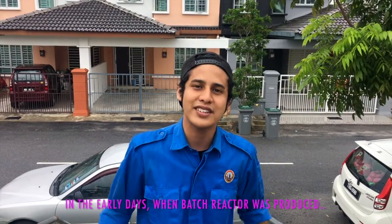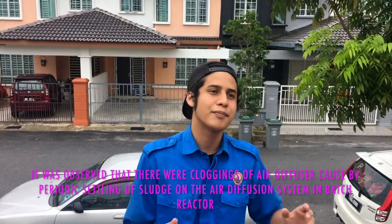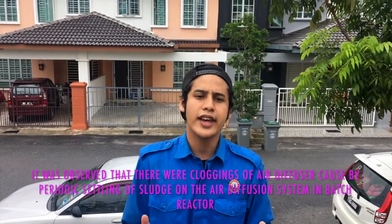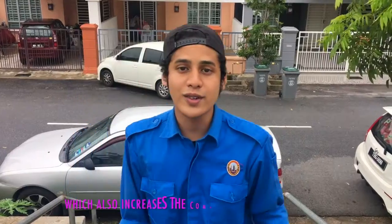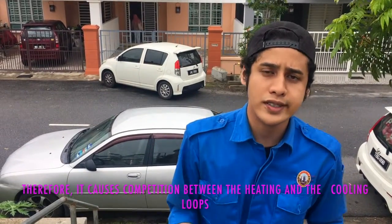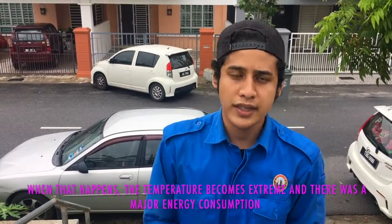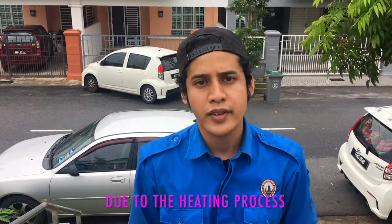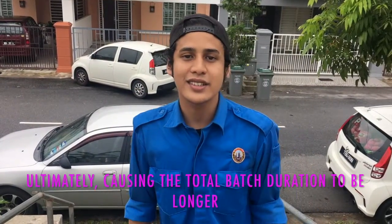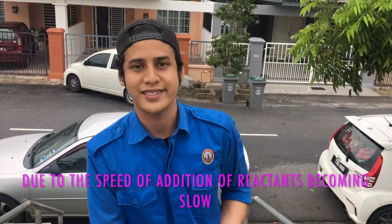In the early days, when the batch reactor was produced, it was observed that there were cloggings of the air diffuser caused by the periodic settling of sludge on the air diffusion system in the batch reactor. It also increases the complexity of operations. Therefore, it causes a competition between the heating and the cooling loops. When that happens, the temperature becomes extreme and there is major energy consumption due to the heating process, ultimately causing the total batch duration to be longer due to the speed of addition of reactants becoming slow at the end of the process.